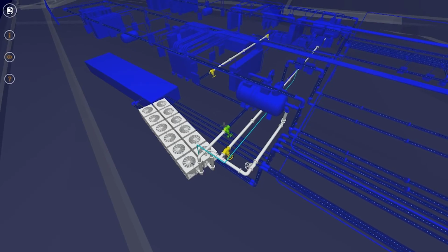We're showing you this on a simple scale, but when you're looking in terms of an aircraft or a ship, we're able to evaluate all of the fluid systems, all the electrical systems, all of the networking, all the air systems, which is actually useful from the standpoint of maintenance, because if you have to tag out a valve and you have to determine what valves to close in order to isolate things mechanically, or what breakers to flip to electrically isolate things, that's a process today that takes a long time when you're using paper documents.